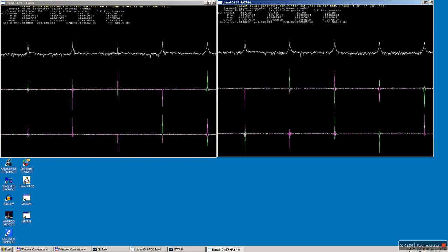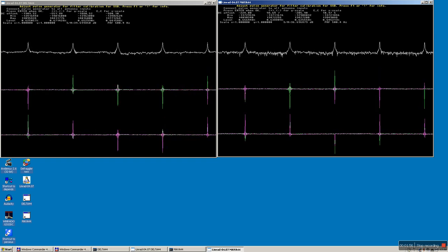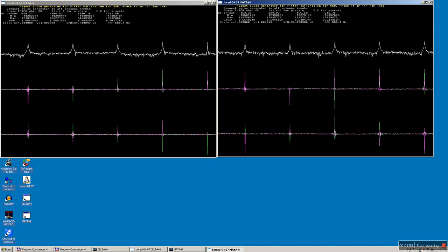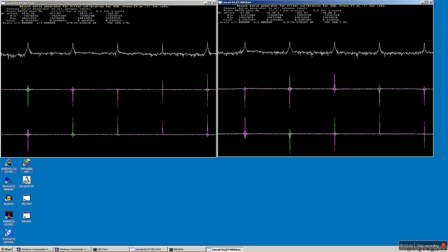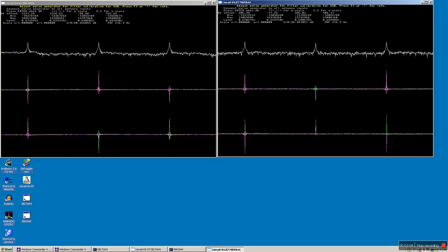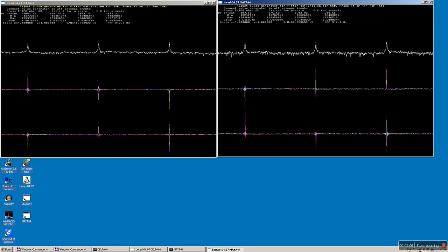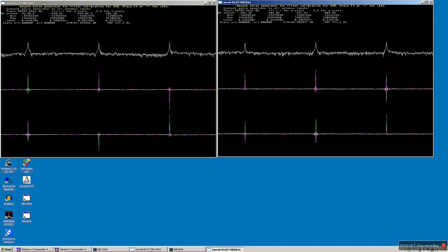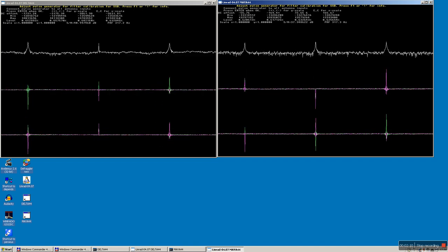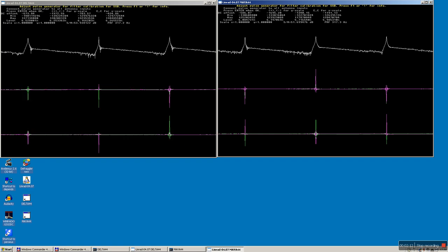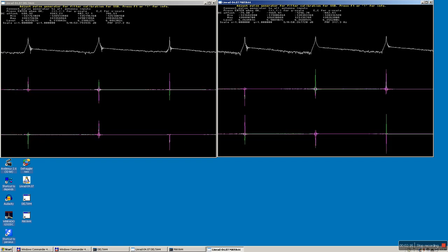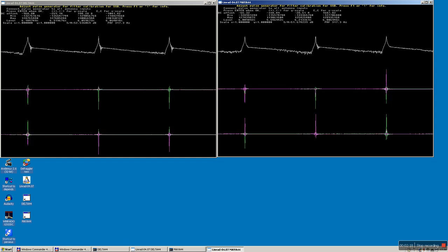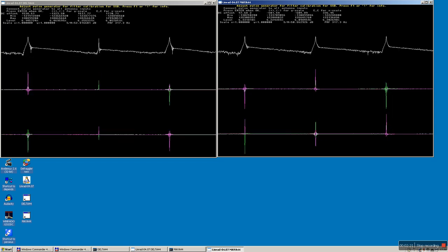The repetition rate is very high. I will make it lower to look at what happens. With somewhat larger pulses, I bring up the level by 20 dB. You can see that the tail of each pulse reaches almost all the way to the next pulse.